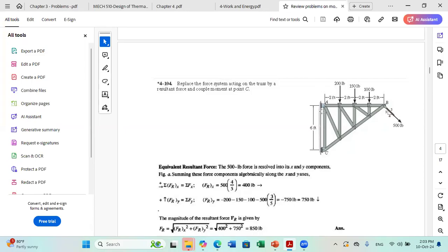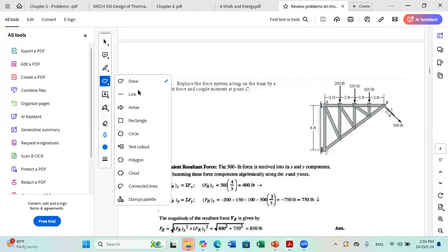Whenever you want to reduce at a point, you should move all forces to the point of interest. But we said that to have an equivalent system, whenever you move a force to a point, you need to add the moment it's producing about the point. Okay? Plus also, I will add something to the problem.